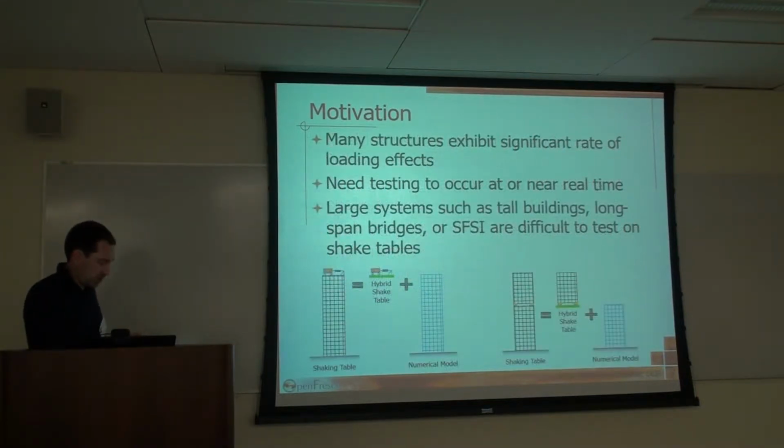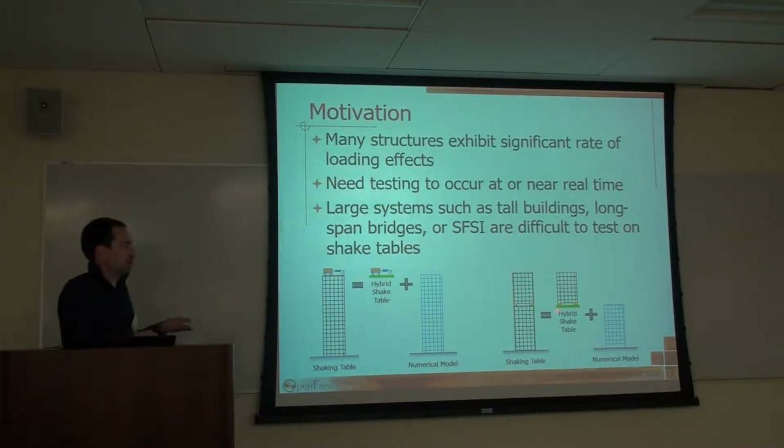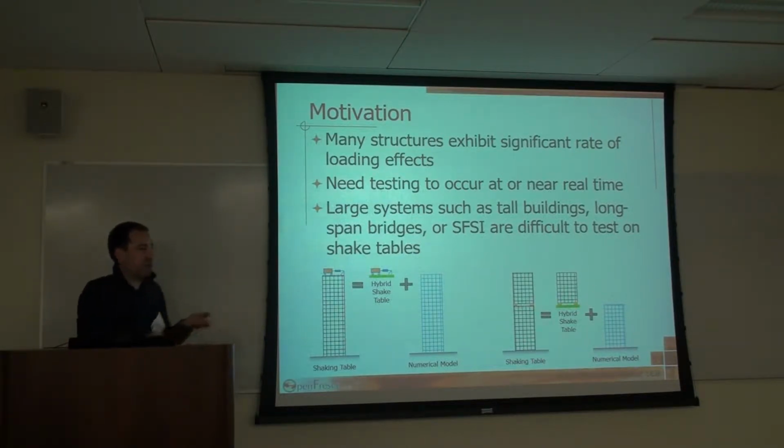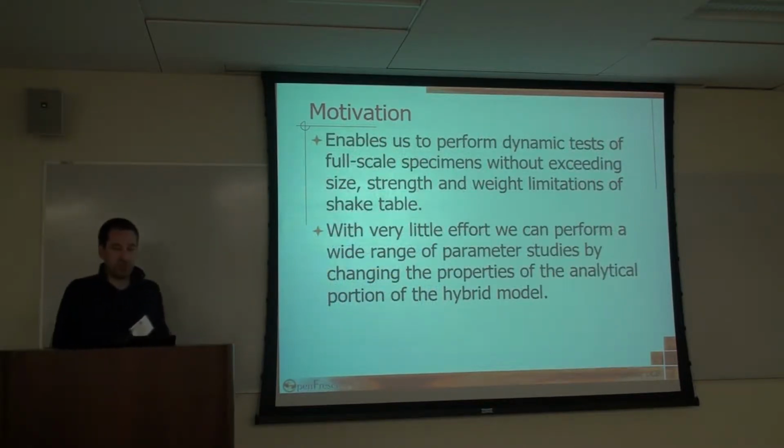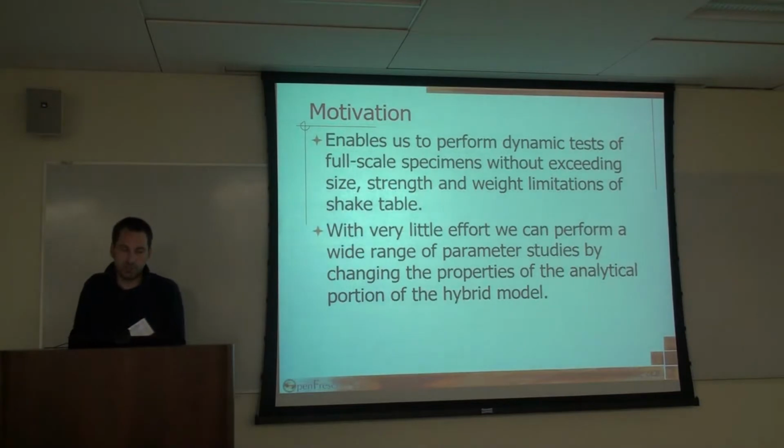If I go back to here, for this structure with the mid-level isolation, we can quickly do parameter studies by adjusting the numerical model here and running over and over. Especially because the top structure with the isolation being on the shake table is non-destructive. So we can run again and again, looking at different parameters in the system and do parameter studies like this. So it's a very nice concept.